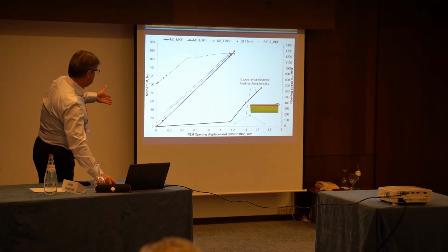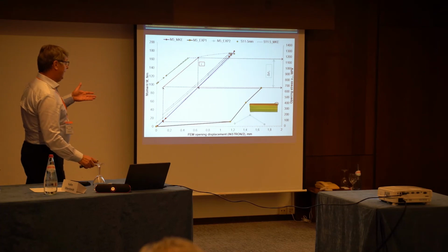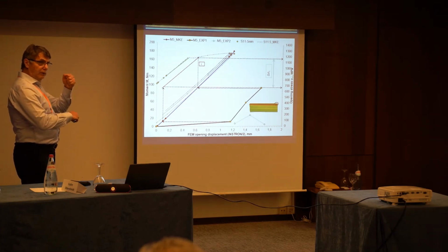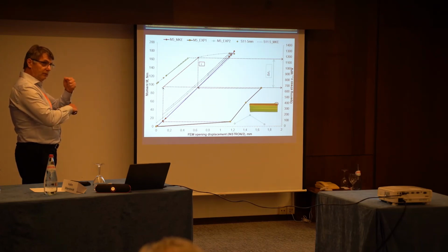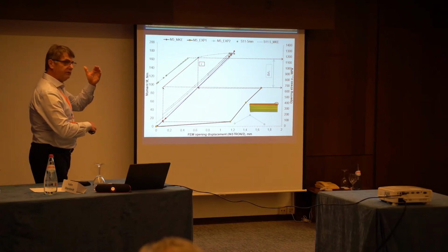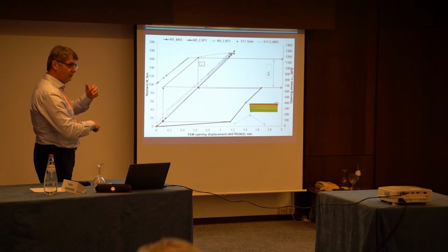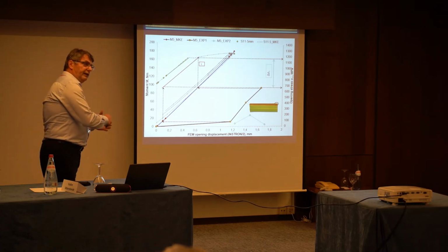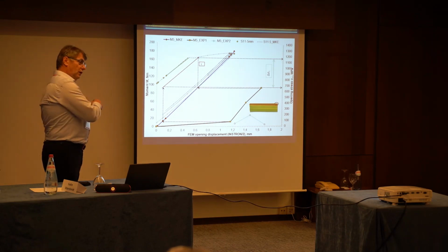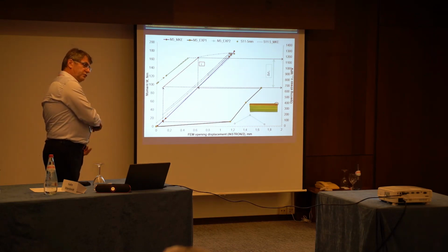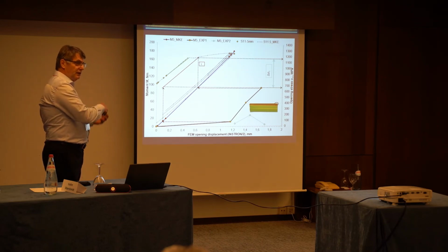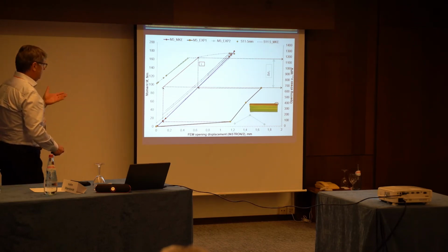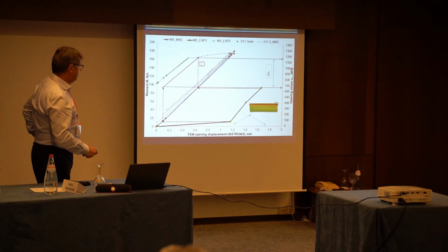But now we want to see what exactly our amplitude is. Theoretically we use R = 0.1, 10%. It's a ratio between minimum and maximum stress, load. But our effective amplitude is different, because the material already had transformation, you already have residual stresses, so you cannot start with 0. You always should consider this load.